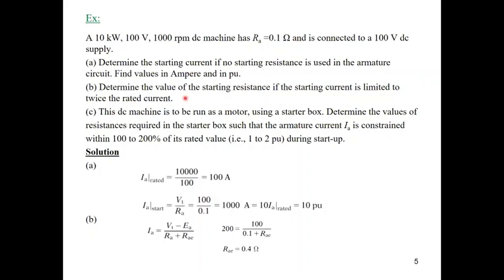Recently we described that most of the protection devices are working for overload conditions between the full load and twice or 3 times the full load current. Twice the full load current is still a safe operation, in a condition that we have to speed up the operation at this high current. So we can operate the machine at twice its rated current, but for a limited time, not for the full time of the machine operation.